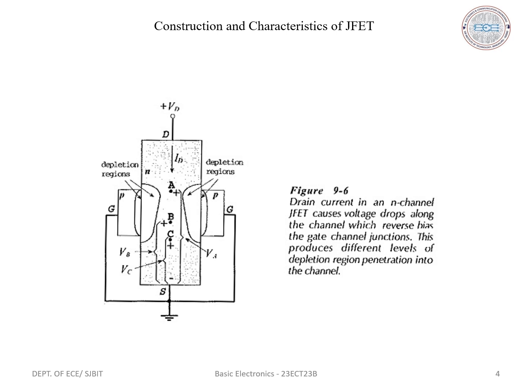FETs are of two types: junction field effect transistors and metal oxide semiconductor field effect transistors. They are further subdivided into P-channel and N-channel devices. So first, we'll consider an N-channel JFET. In this figure, the operating principle of an N-channel FET is shown. An N-type semiconductor material, referred to as the channel, is sandwiched between two smaller P-type materials called gates.